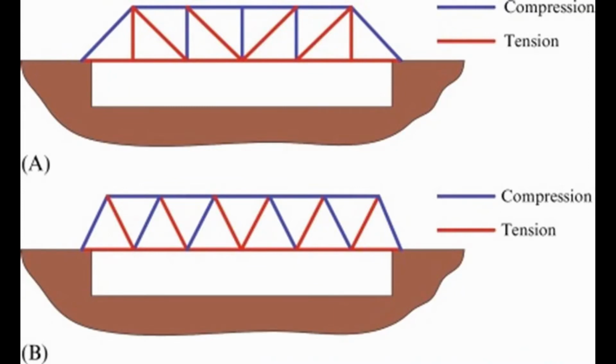One other thing to consider is that the shape of the truss actually makes a difference. Sometimes it's hard to tell just by looking at a truss which beam segments, called members, are in tension and which ones are in compression. Although every truss design is different, you can generally assume that just like in the slinky example, the members at the top of the truss will be squeezing in compression and the bottom members will be stretching in tension. Engineers can do calculations to find out exactly which beam segments are in tension and compression and exactly how much force each member is carrying, but we don't really need to worry about that too much for this activity.